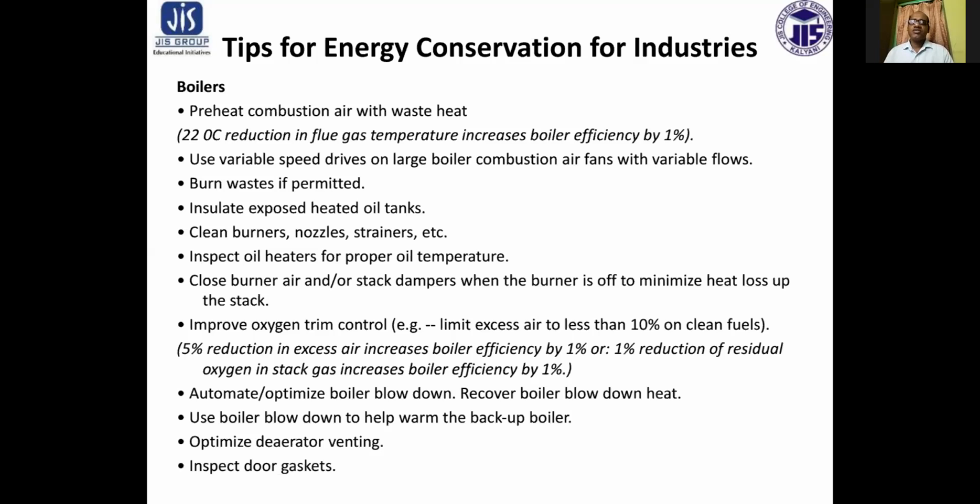Clean burners, nozzles and strainers, because sometimes these are choked and cause malfunction. So from time to time we need to clean the burners, nozzles and strainers. Inspect oil heaters for proper oil temperature.